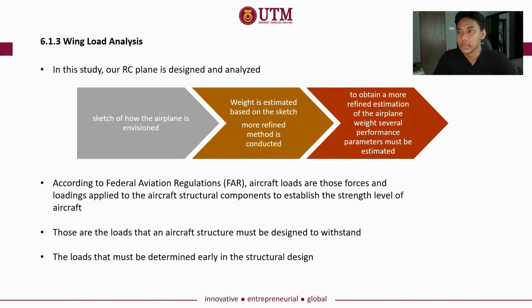The last one is to obtain a more refined estimation of the airplane weight. Several performance parameters must also be estimated. According to the Federal Aviation Regulation, aircraft loads are those forces and loadings applied to the aircraft structural component to establish the strength level of the aircraft. Those are the loads that an aircraft structure must be designed to withstand.